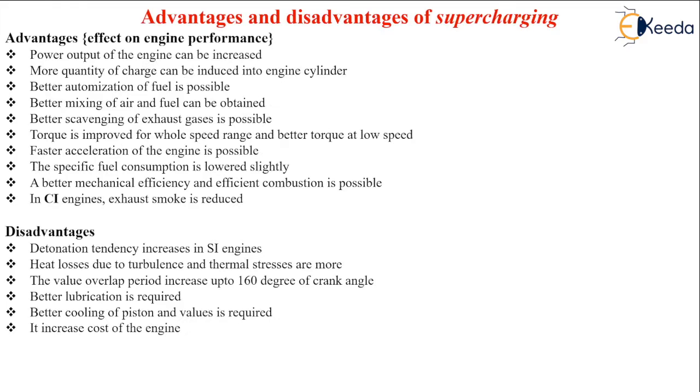There are certain advantages and disadvantages associated with supercharging. First, let us look at the advantages. The power output of the engine is increased, as we have already seen the reason behind it. Then more quantity of charge can be induced into the engine cylinder. Why is this? Because the air or charge will be compressed into the same capacity of the combustion chamber. Because the charge or the air is compressed, a larger density of it can be accommodated.